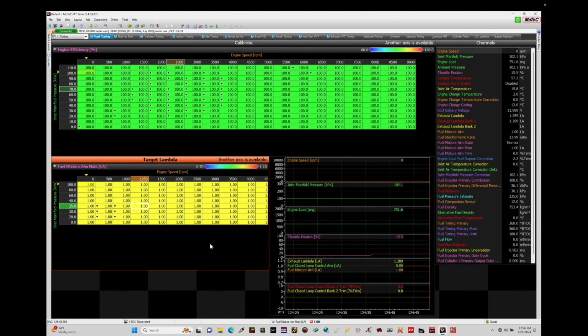Okay, so let's get started. We're going to be taking a look at how to dial in our fuel tuning within the Motec M1 as quickly as possible. We've covered a lot of concepts and topics within the training course up to this point. Now I'm going to show you how to dial in your main VE table as quickly as possible, getting your charge cooling set up, getting your injection timing sorted out and optimized for the engine you're calibrating,